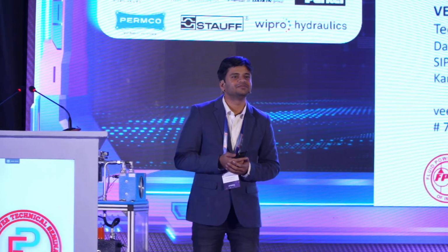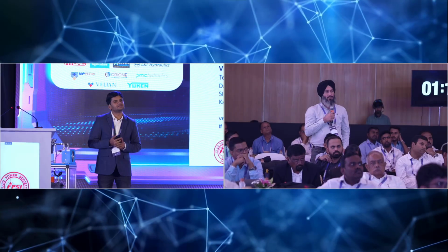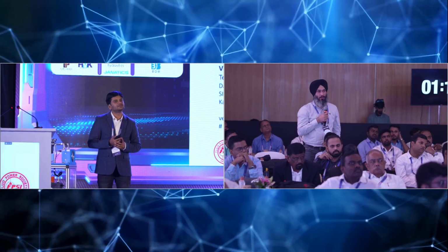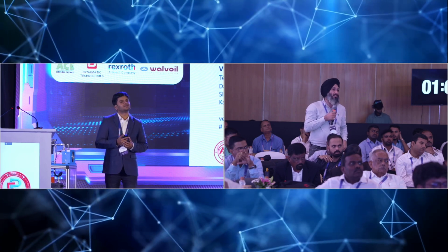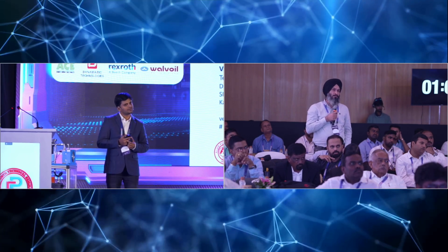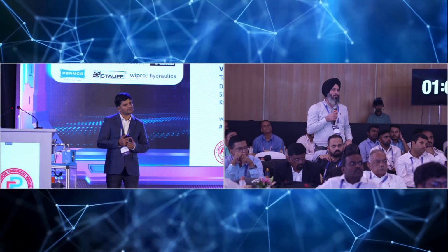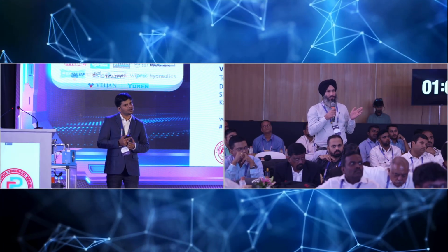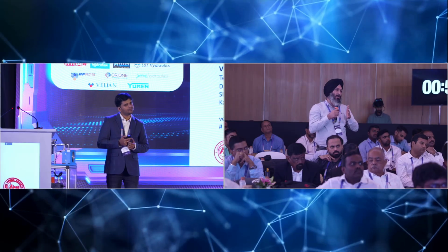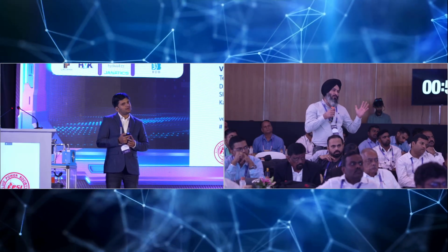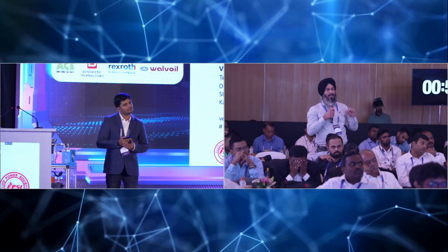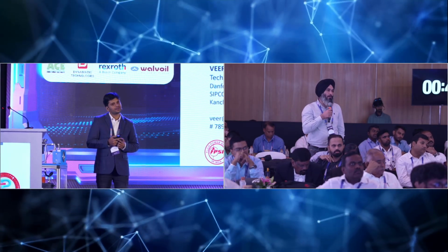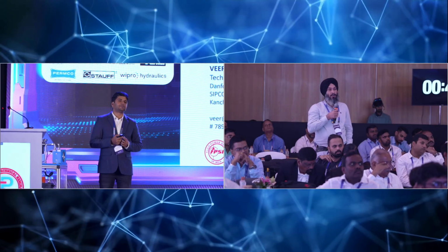I'm Ravinder from Epiroc Nasik. So the question is, generally piston pump manufacturers don't recommend going below 10 cSt of fluid viscosity. Water may have near 1 cSt. So how are you making sure that the boundary film is properly made on the interface of the barrel and the port plate, and on the swash plate and the pistons? How is the life of the pump ensured, because that's a very critical parameter when we talk about selecting a piston pump for a hydraulic application.